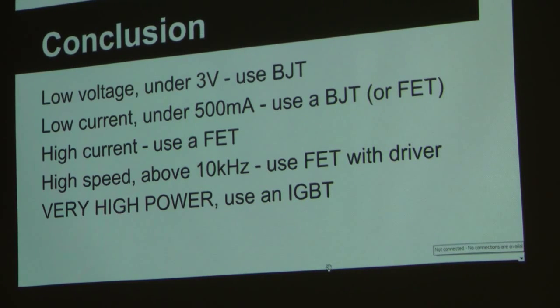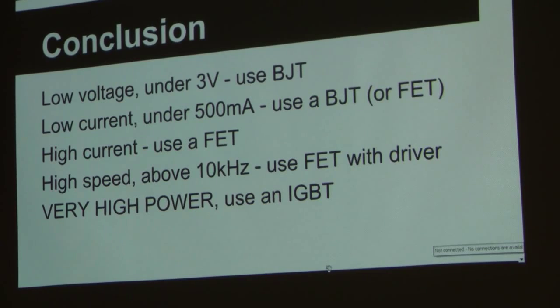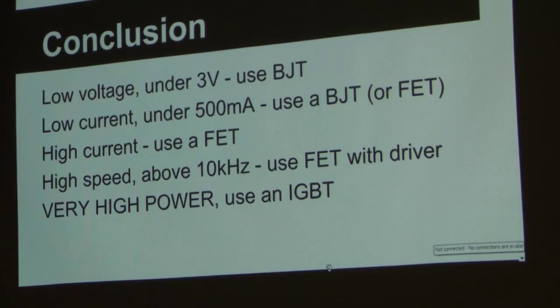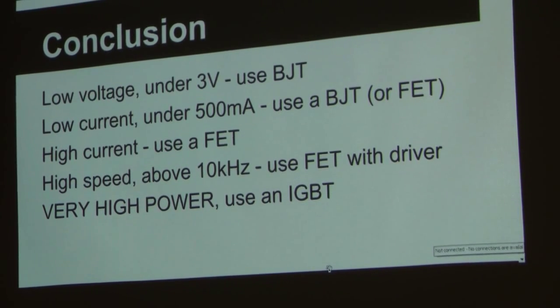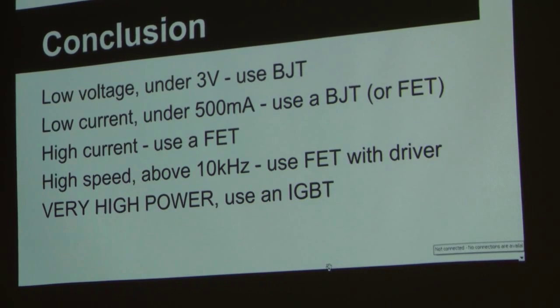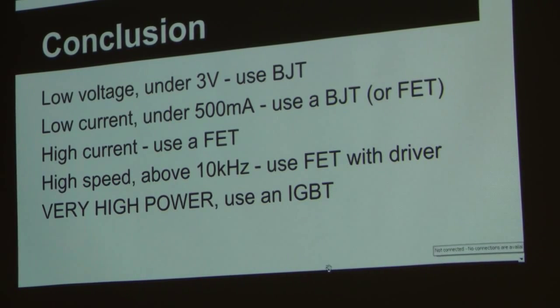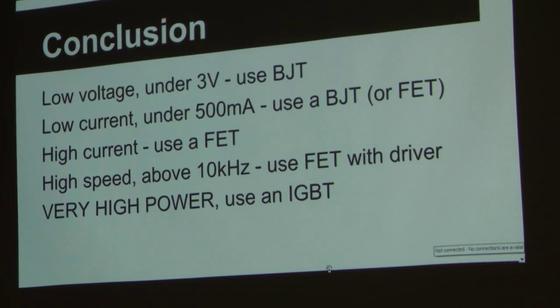I was actually doing a project where I was trying to use a 1.5 volt pager motor, and trying to switch that with a FET was just exceedingly challenging because I didn't want to put a different circuit on there for doing current limiting and doing a more complicated thing than I needed to. It was battery operated, one battery. But when I used a BJT, worked like a charm. The BJT only needed 1.6 volts.